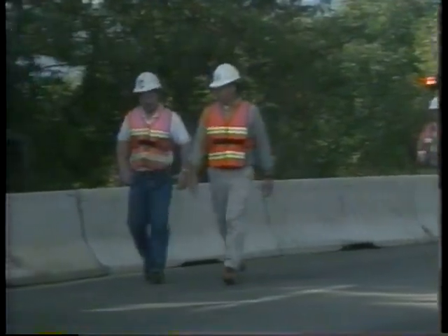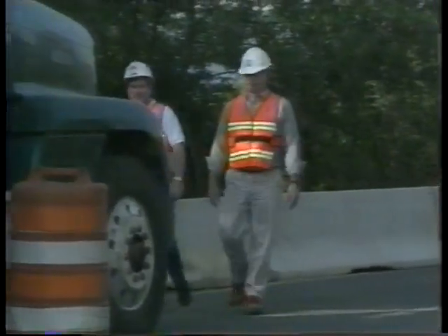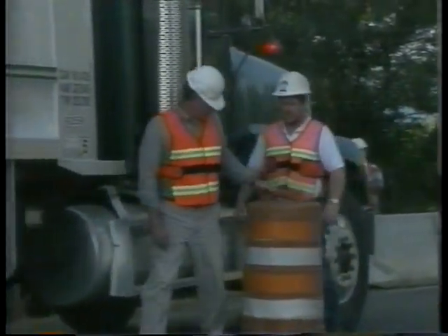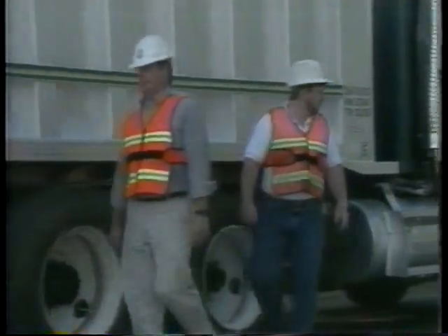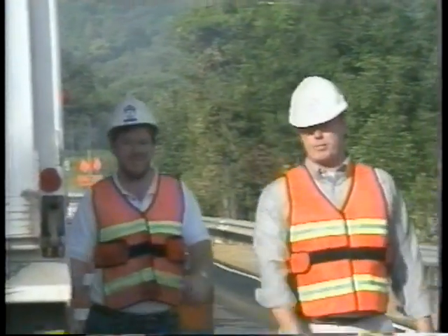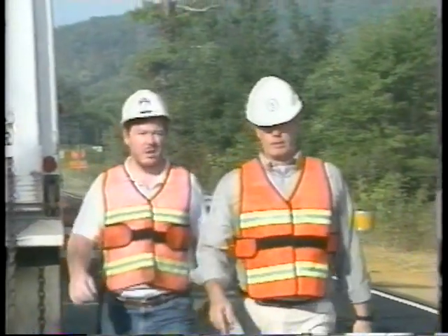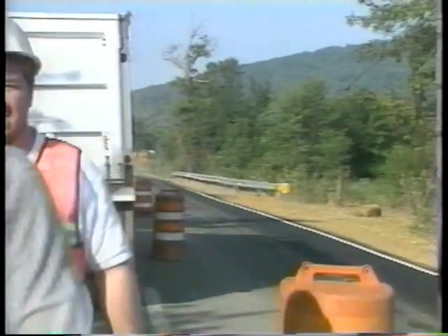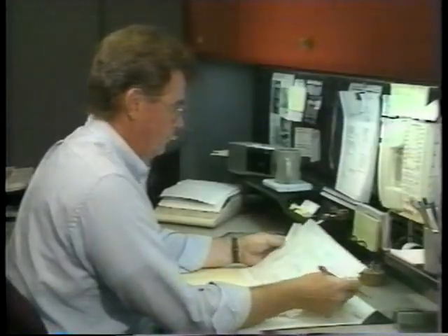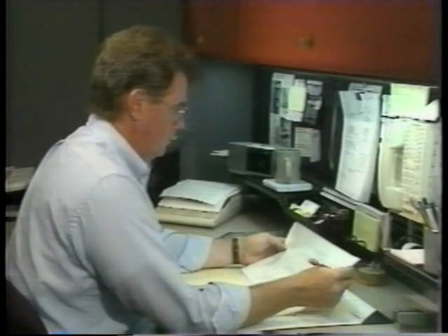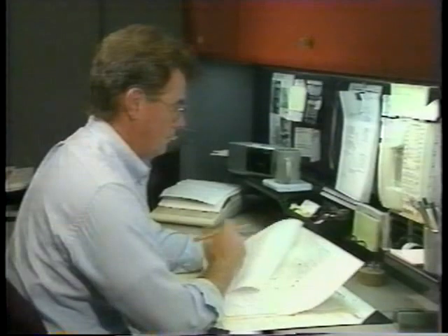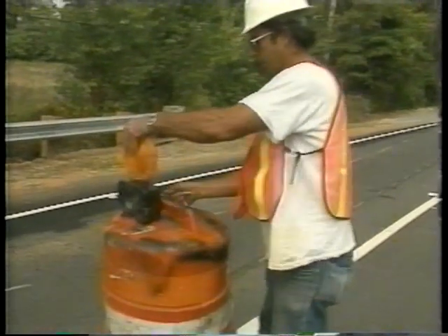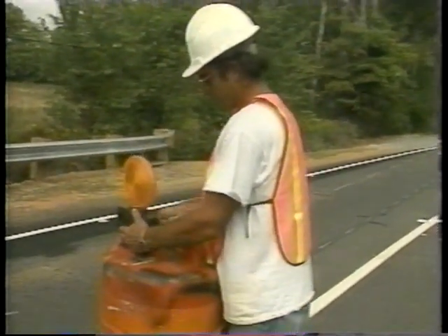Inspectors are a key element. They must be properly trained in work zone traffic control device application, and they must have the authority to modify traffic control when necessary. As part of their inspections, they must consider varying traffic conditions such as traffic volume and weather. And they must periodically review accident data to help them constantly improve safety conditions. Maintenance problems discovered by an inspector should be remedied as soon as possible.